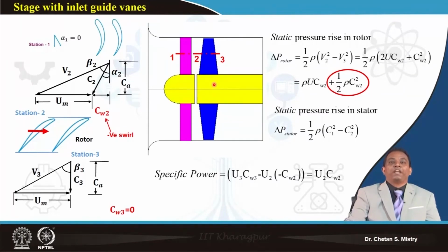In a rotating configuration, changing this pitch is very challenging. So that can be modulated by using this inlet guide vane, that is, you have modulation of your mass flow rate.